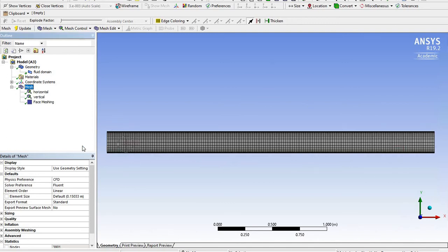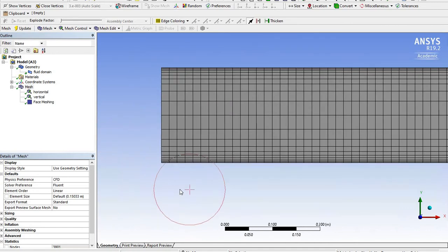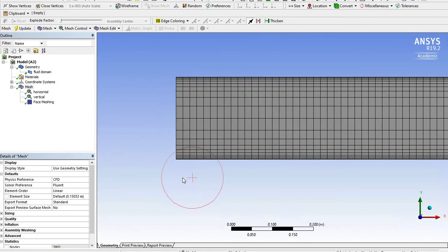So we're done with the mesh. Again, you can always play around. But start with a standard mesh, which looks good. Just start your simulation with one mesh, and then you need to verify, because we don't know if this mesh is good enough for our problem. We cannot say that. Okay, there are some considerations from some of the literatures, but again, for this, you just want to learn how to use ANSYS, and you're not going through the literatures to learn the software.